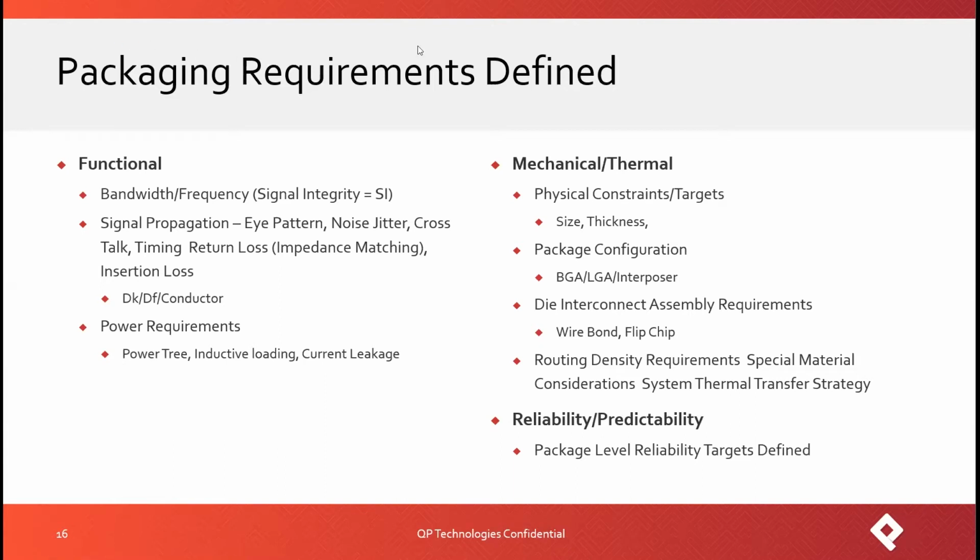There is a question about the options for CMOS camera chips to be packaged. To be honest with you, ceramic for cases like that is always going to be a better option for low volume or prototyping. Otherwise, there are certain costs associated with that, and also certain limitations as far as availability of given package options. Depending on the requirements, you can pretty much use any of the packages that we've just touched upon.